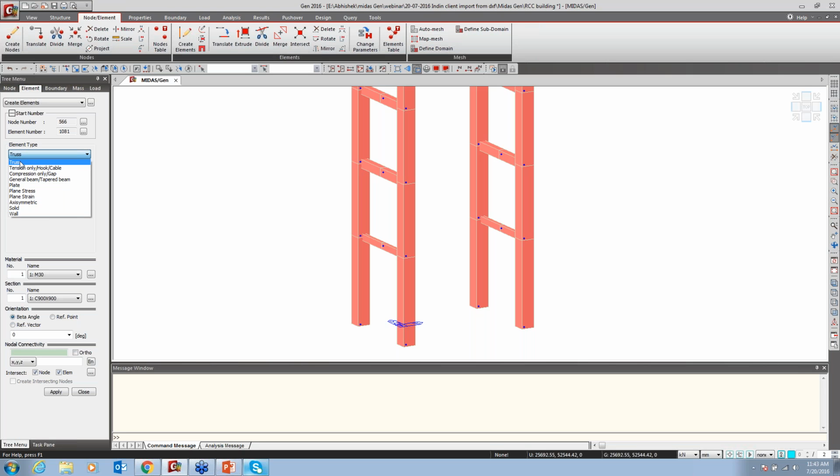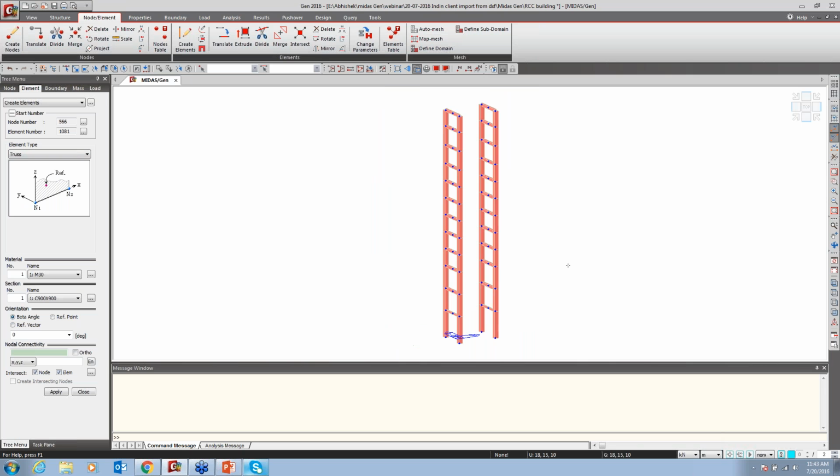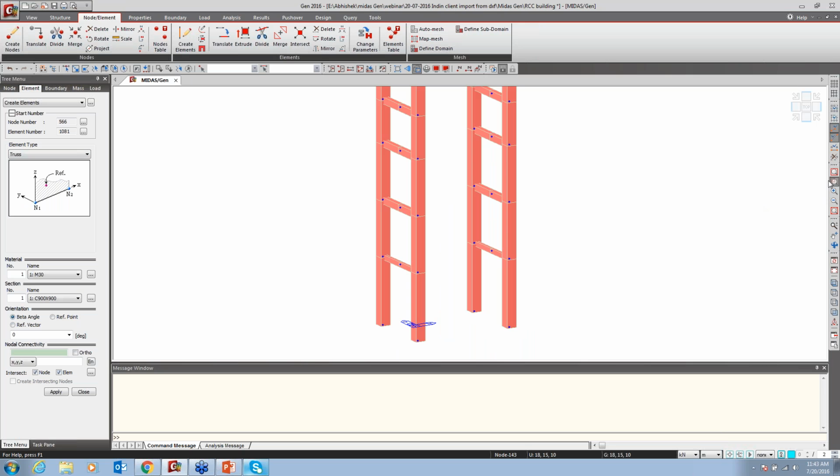Okay, sometimes in most of the programs what we did, we model as a beam element, then we released it so that it will consider only the axial forces, and according to that we did. But in MIDAS Gen we have the direct option. You can directly use those options for the generation of the elements. So I will just say truss element M30, say BR, and click on the nodal connectivity option, and I just click first box and incline.